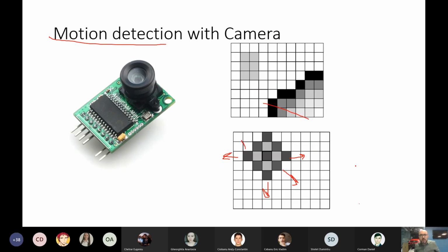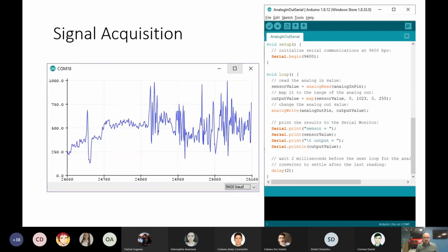So finally, from the interface of the system, we'll have a sensor here, and on this side, let's say, this line of code is how we measure. We just do analog read for the analog signal, digital read for the digital signal, and pulse in for the pulse.